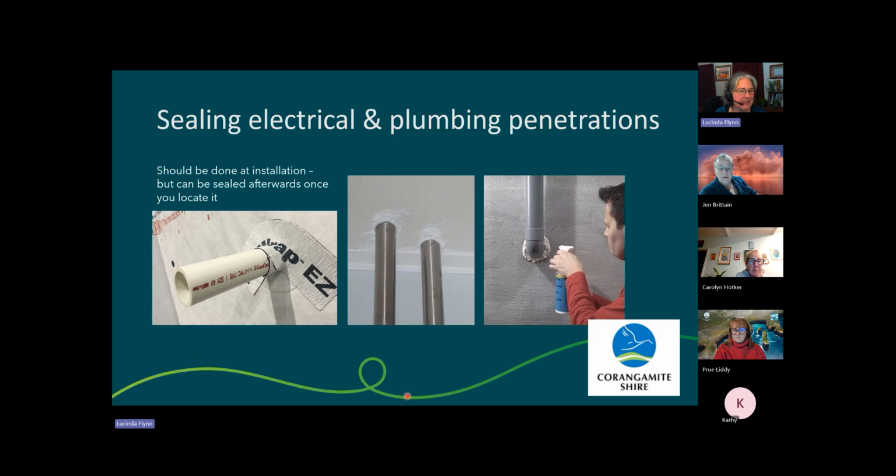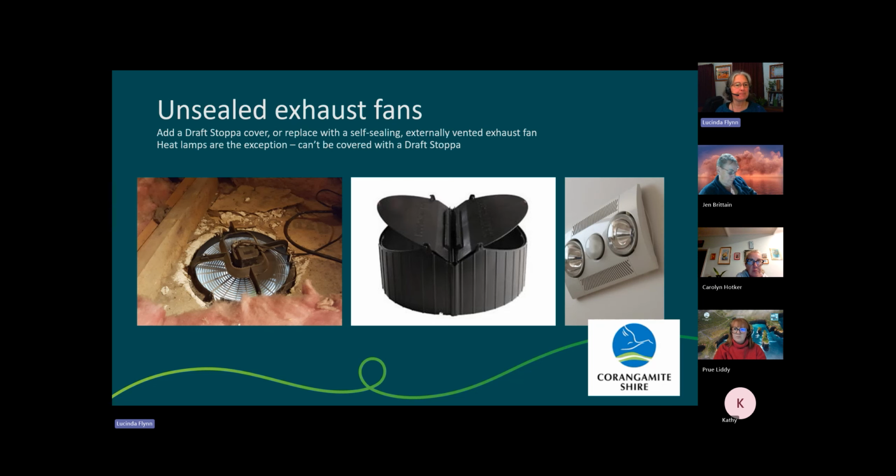You can do sealing with tapes or plaster or foam, expanding foam. So you can do things after the fact. It's much better if the tradies do it then and there, because they've got the materials to do it, and that way you never have a problem in the first place.